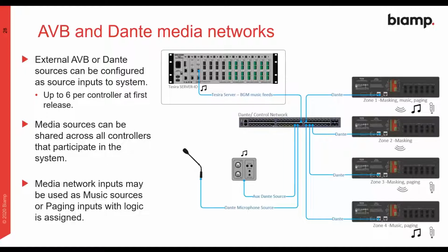Depending on how it's set up, those can also be done by appropriately naming the host name and the channel name, and it will set up the routes for us on Dante. AVB, still, upon release, you will need to get an AVB controller and route those manually. That'll eventually be an automated process built within the file. But upon the release that's going to be on the streets soon, Dante will automatically route if you get everything right with the host name. You enter the host name and all the device info, and the routes will be made for you.